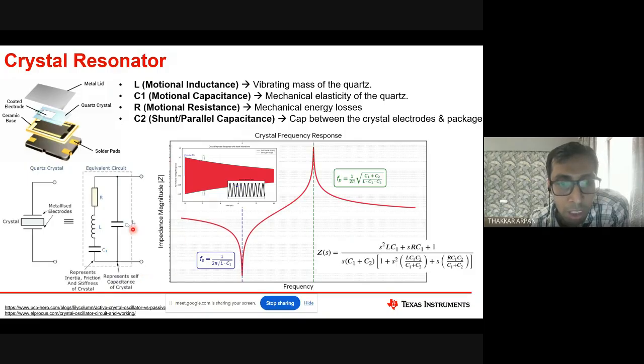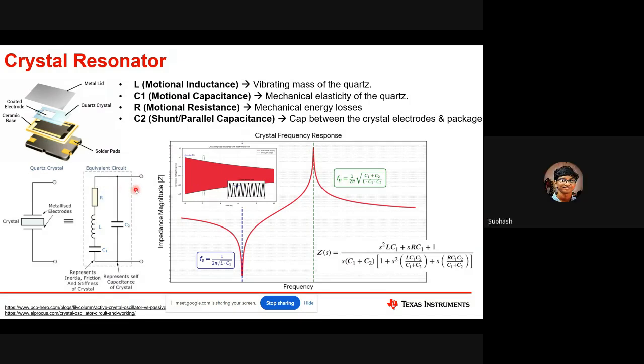So then you have to see in a large signal sense, over the entire cycle, effectively how much negative R it is providing. Those are a bit complex analysis, but you will learn that in your master's course. But essentially, that's how it happens. So the stabilization happens the same way it happens in a regular LC oscillator. Yes, amplitude stabilization is controlled by GM.